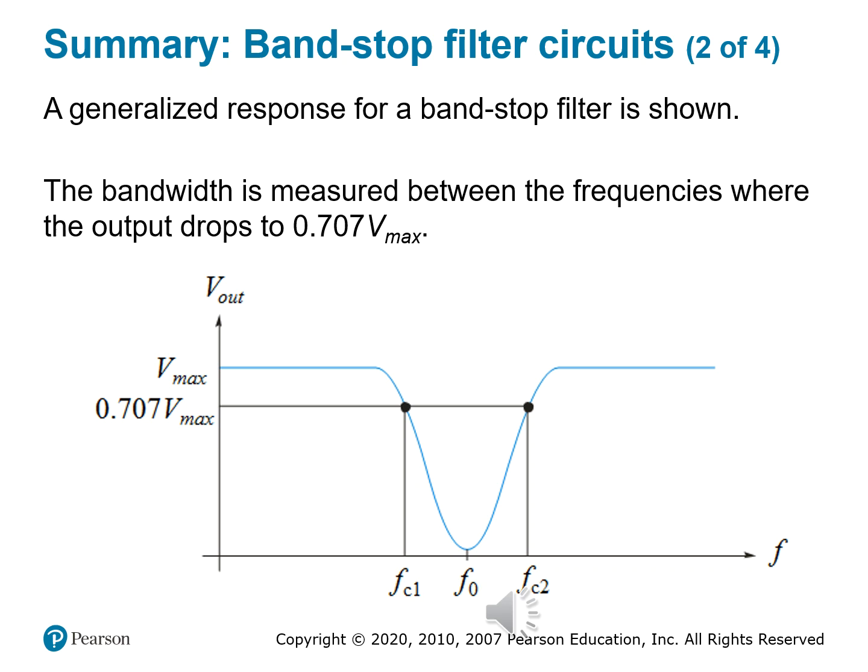Again, just as a reminder, 70.7% of the maximum voltage in is equivalent to that negative 3 dB threshold. So what's actually being measured? That dip that you see is where unwanted frequencies are effectively squashed. Like they're just thrown down that chasm. We can call the span between both FCs the bandwidth, from one critical frequency to the other, in this case FC1 to FC2. And this is the key metric.